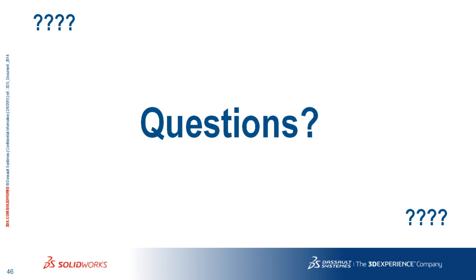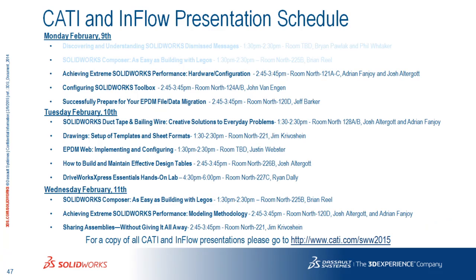Well, they said years ago, before I worked there, they had it where it made configurations. But the file itself got so big that they felt like it was slowing down assemblies. Right. The file had 10,000 configurations. In the last couple of versions now, in the tools options, there's a checkbox that says purge configuration data. Flip that on, that'll go away. 2015 files are much smaller too, so we have seen file reduction quite a bit actually in most applications.